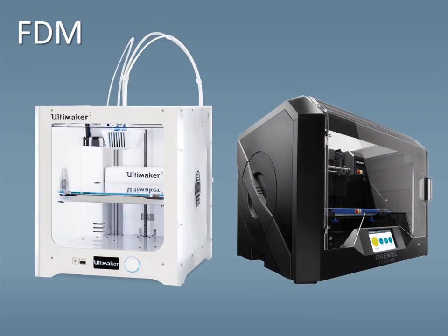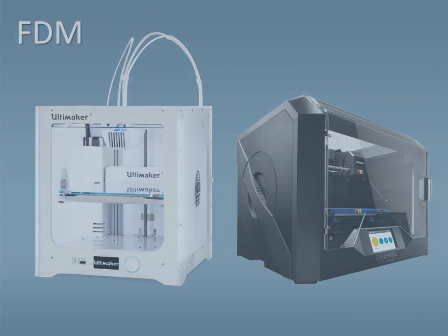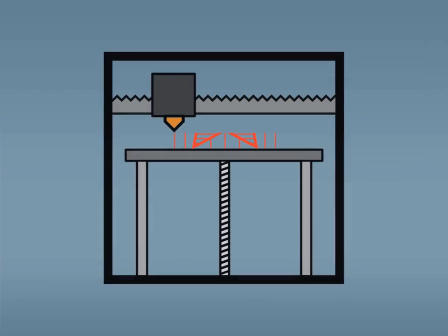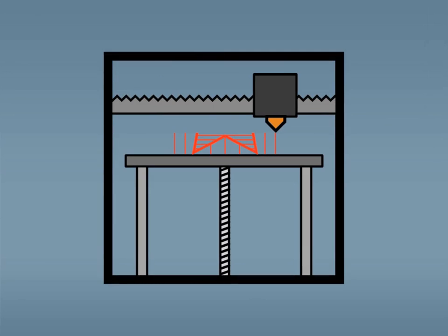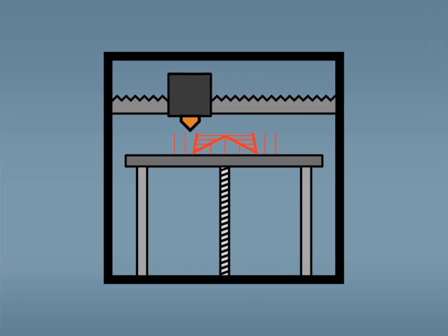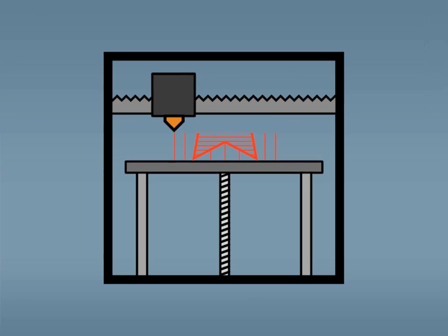To begin, I'll discuss which types of materials are used for fused deposition modeling printers, or FDM printers. To quickly review, FDM printers push a strand of plastic through a heated nozzle. The temperature of the nozzle allows the plastic to become soft and malleable and can be printed in the shape of the part. The material must also fuse to the plastic printed on any lower layers.